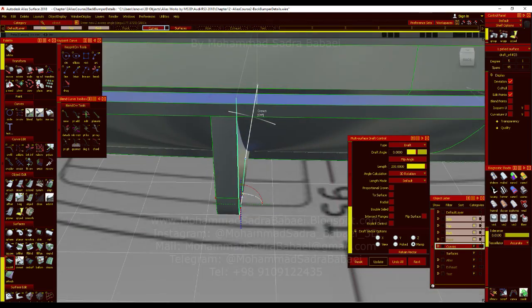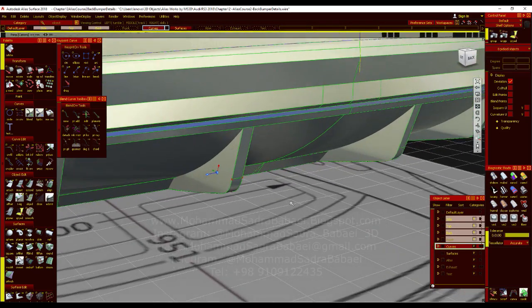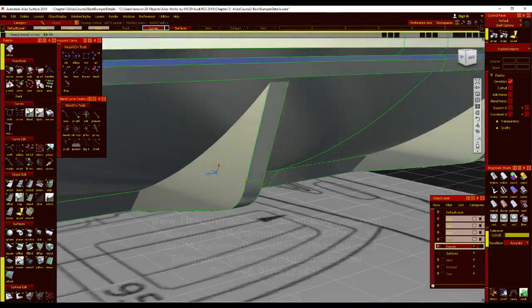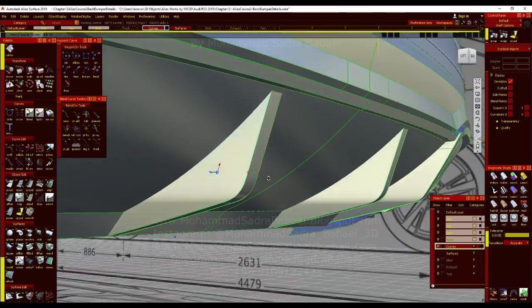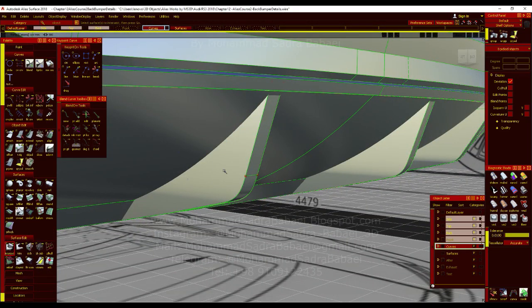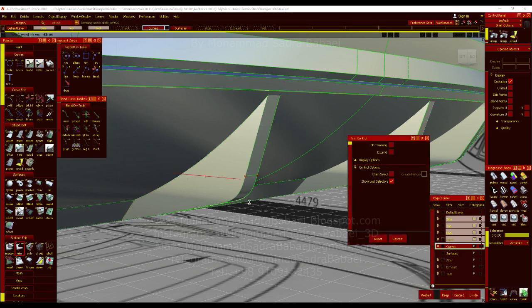So the thing you can do is duplicate that and mirror it to the Z and X plane, so you can move it here and also have the same value, same surface tilt. Now we can intersect them together and trim that. Okay, it has just trimmed.